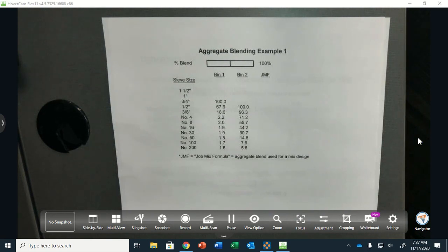So it's very important that the gradation for asphalt is actually even more critical in asphalt than it is in concrete, okay? Because that asphalt, it's just aggregate, air, asphalt. That's it. Glued together. And it gets heated up, okay? So what we need is a very specific, well-graded mix. Remember those terms, poorly graded, well-graded. Poorly graded is one size, well-graded was several sizes. And then there's gap graded where they miss sizes, okay?